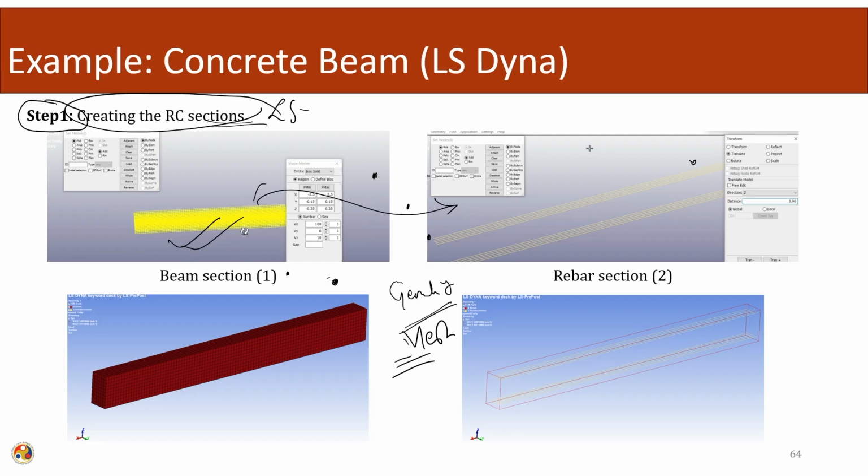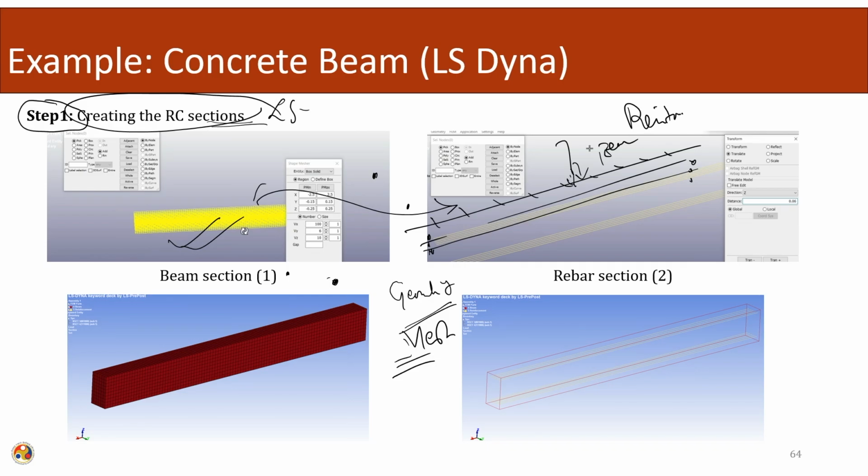After creating this, we can switch off the system and then create parallel lines like this. We have to create the nodes, and from the nodes we can join these lines. To these lines we can give the property, mesh them, and give the properties of the beam. So, this will represent the reinforcements. Similarly, we can make the top reinforcement, and at the bottom we can create nodes like this, join the nodes with the lines, and mesh them using the beam elements.